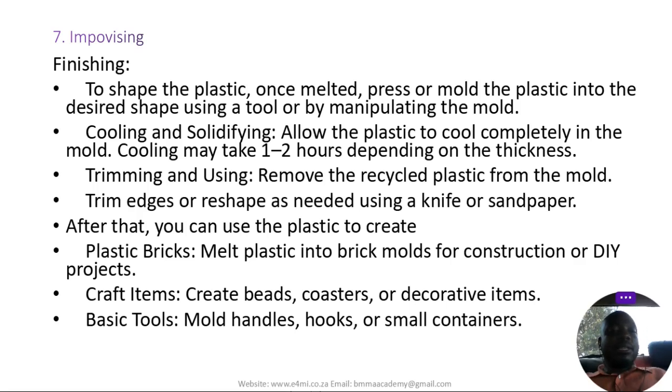So after that, we can then trim and use the plastic. Remove the plastic from the mold and then trim the edges or reshape them as needed using a knife or sandpaper. After that, you can use the plastic to create plastic bricks, craft items, or other basic tools. You can use them to create beads, coasters, decorative items, brick molds for construction, or other DIY products, depending on what your clients need.